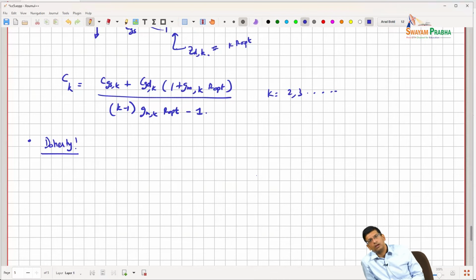Yes. Stacking. Can we keep on stacking, or is there a limitation? So what you find is that as you stack more and more devices, you're basically creating a situation where the parasitics start impacting the design. And remember, as you go from 3 to 4, you aren't doubling, right? You're making the improvement 4 over 3, right? And that basically starts disappearing a little bit as you increase the stack and start seeing parasitics.